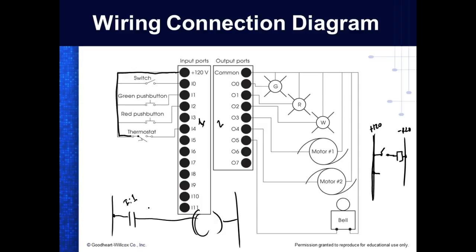And you don't have to put the input module right beside. You could put the input module out at slot 4, right? You understand? It's just that when you write your program, you would address it at slot 4. So we can move these around. There's nothing in the rule book that says the inputs have got to go in slot 1. It's up to you, right? Understand that?